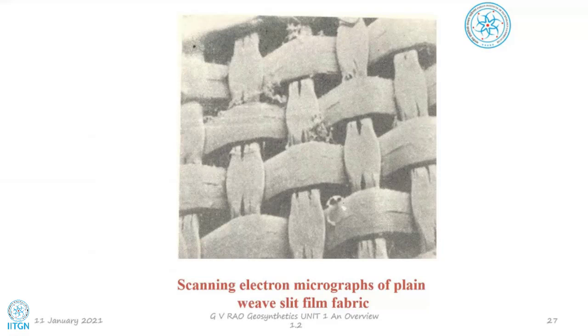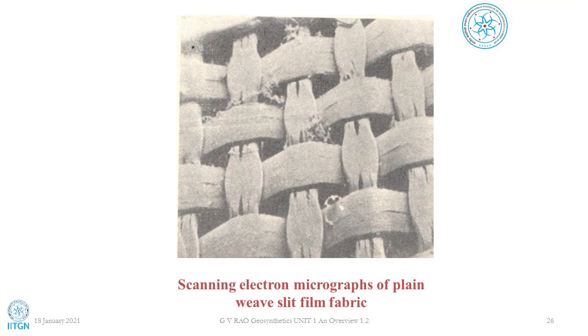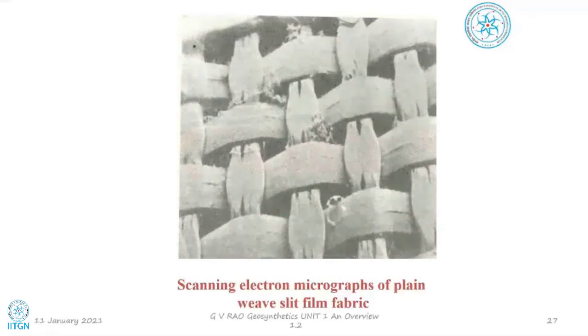But now this geotextile is passed through hot rollers, and once passed through hot rollers and compressed a bit, what's going to happen? The projection is getting melted, and this is what is happening. It became flat. That process is called calendering. It's going to change: earlier it probably had higher friction, now it becomes lower friction. So we are able to see that the properties are decided by the manufacturing process.